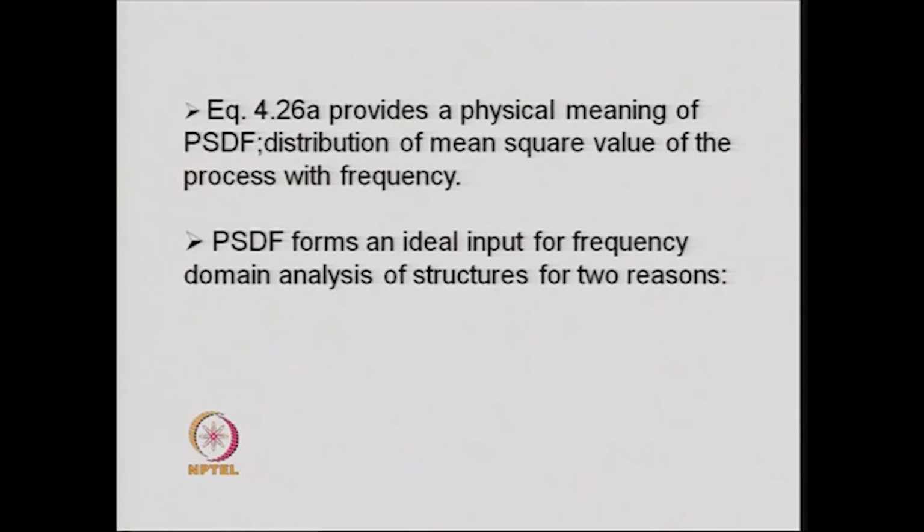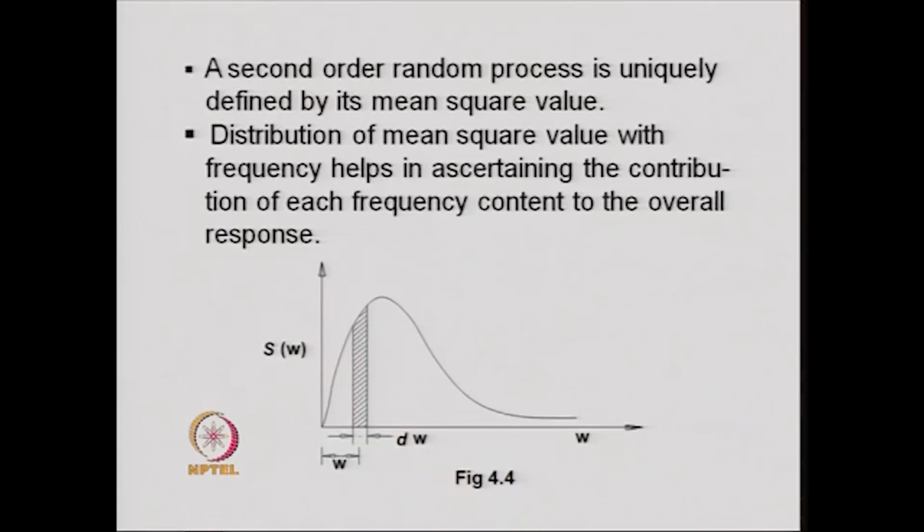Now, the PSDF, the power spectral density function, forms an ideal input for frequency domain analysis of structures for two reasons. Firstly, a second order random process is uniquely defined by its mean square value.